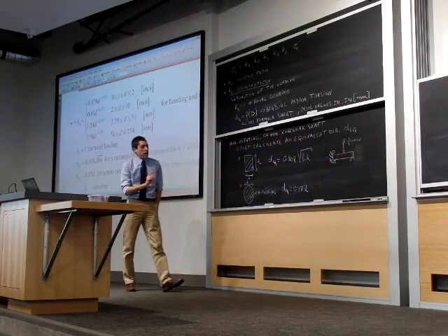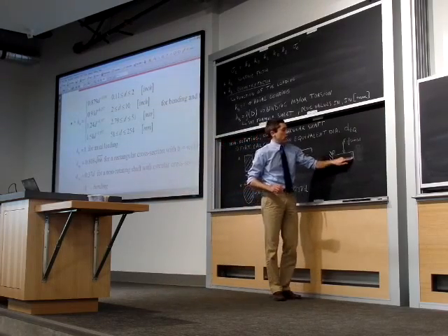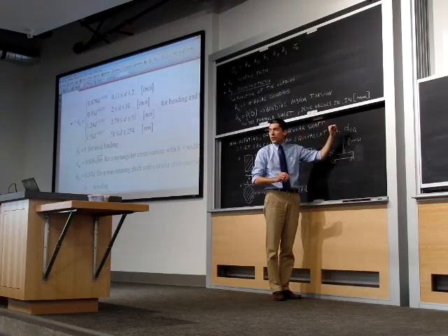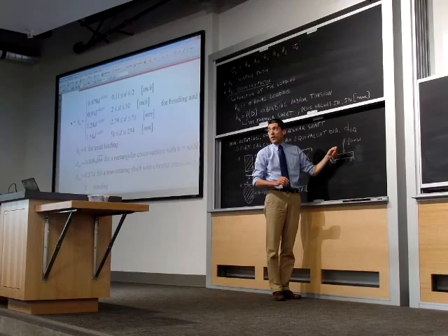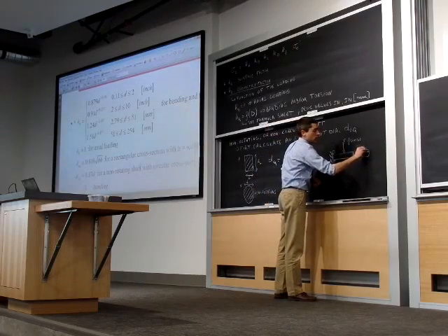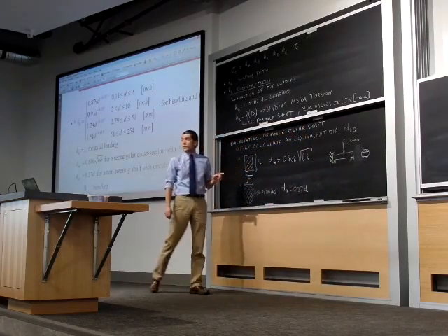And you see now that my maximum stress in case of the rotating element is going to be some kind of circle around the contour of that shaft, but in this case my maximum stress is not going to be a circle. It's going to be some region at the top and at the bottom of my shaft. That's where my maximum stress is going to occur.